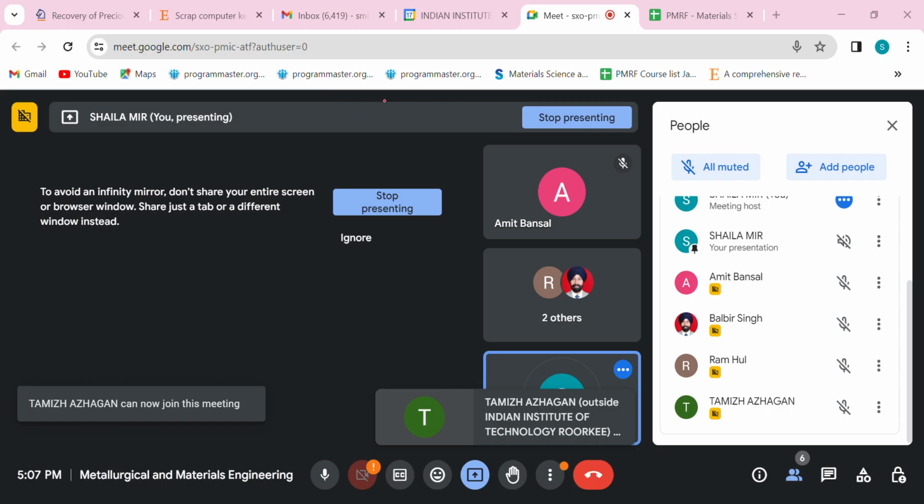Okay, so if you have seen a developer, I think option C could be the right answer because when you are putting a developer on a material, the purpose of the developer is that it should pull out your penetrant out of the defect so that it can be seen, right? So not only it should provide the contrast, but it should also be able to pull back your penetrant from the defect.